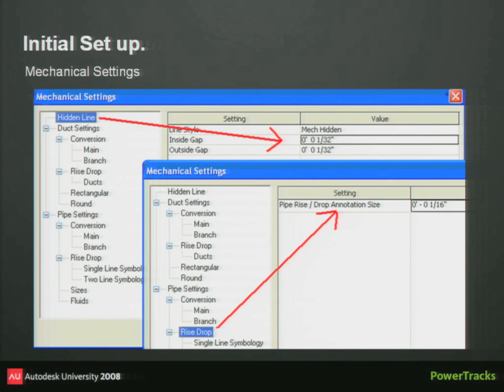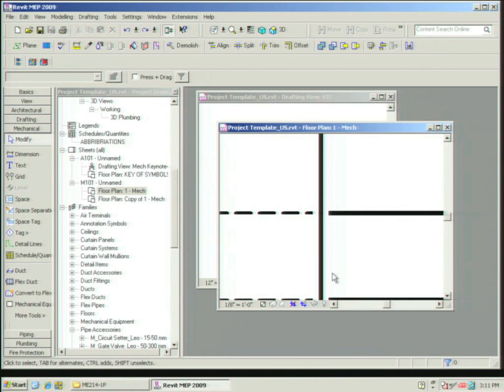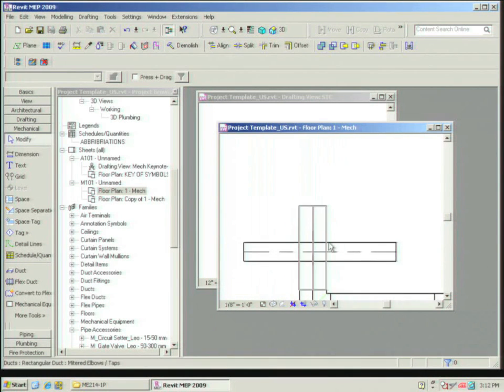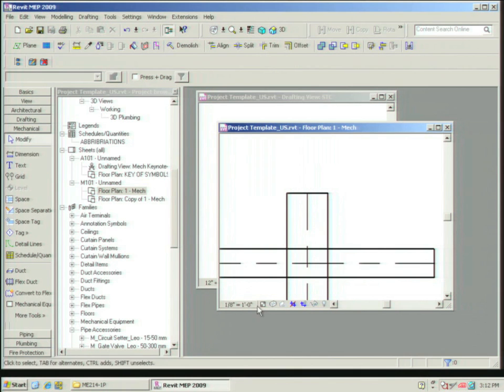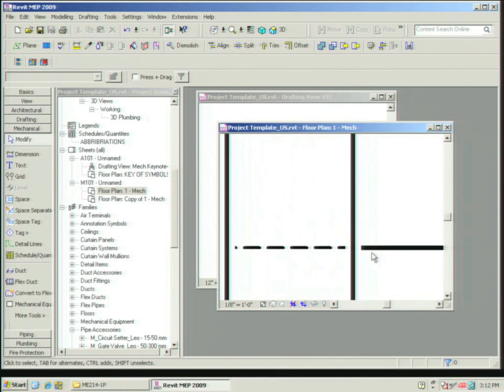Yes? When I do that, I don't actually see the hidden lines underneath. I don't see the hidden lines at all. Is there another setting somewhere? Well, yes. In order to see that hidden line, it shouldn't be a wireframe. For instance, this line setting has to be hidden line. If it's on the wireframe, you don't see it. But this view is faster. I'm going to touch that part later on, but it can't be wireframe in order to see that hidden line.